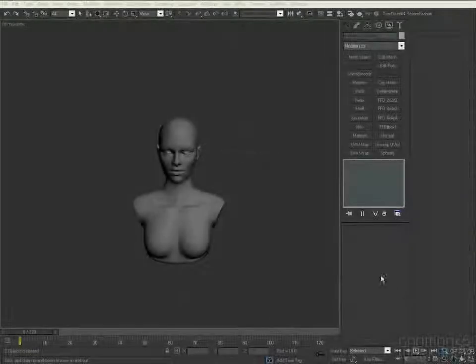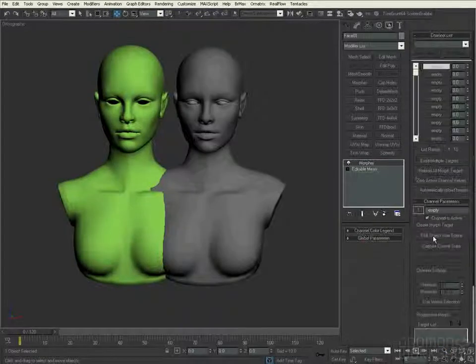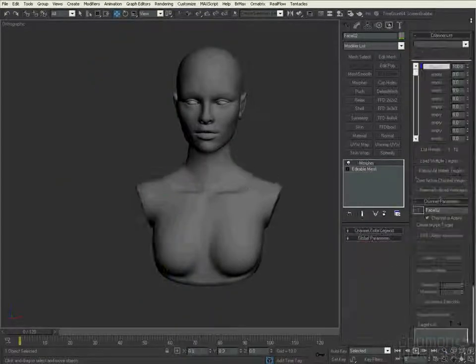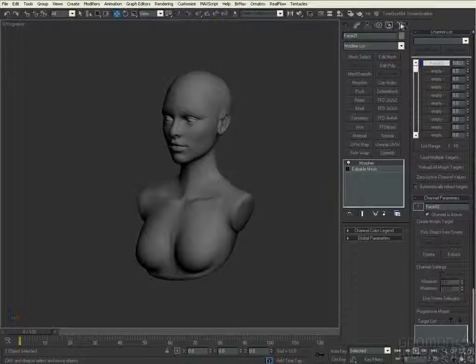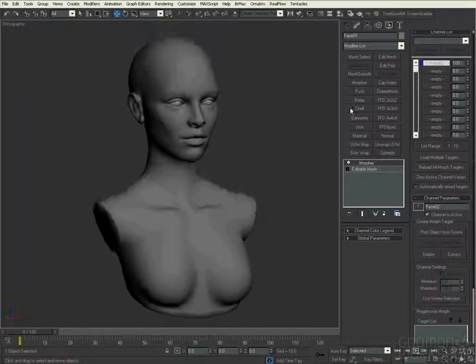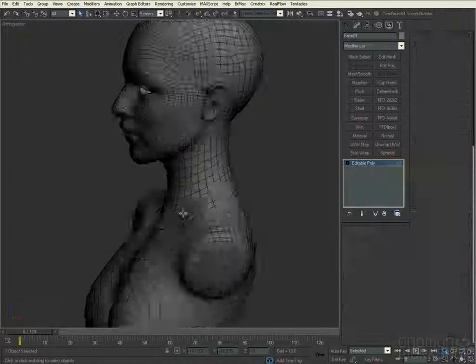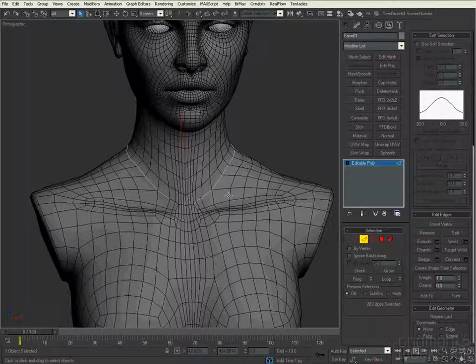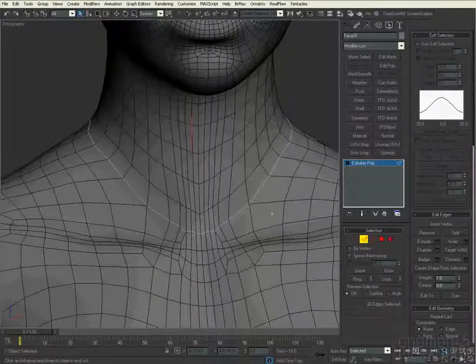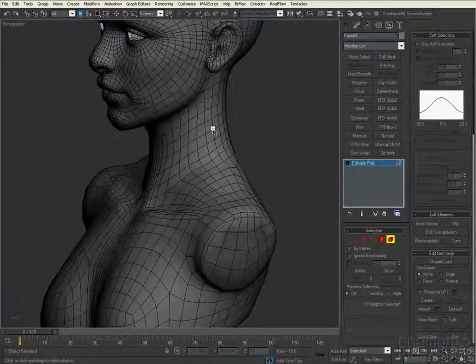In this section, we'll learn how to unwrap your model and do a UV layout. So we got the model from the previous section, and we'll morph it and collapse it to editable poly. And the first thing I look for unwrapping is the seam, and I use the poly tools in Max